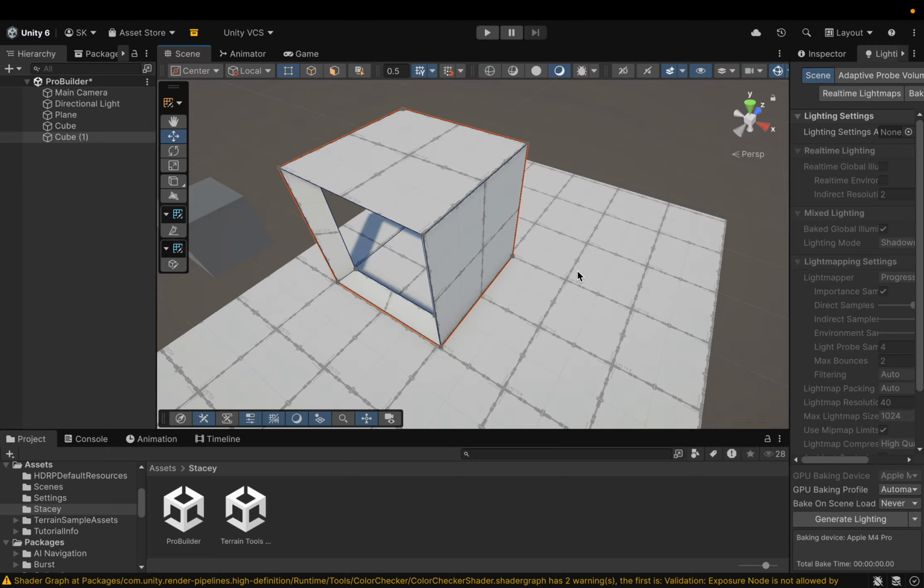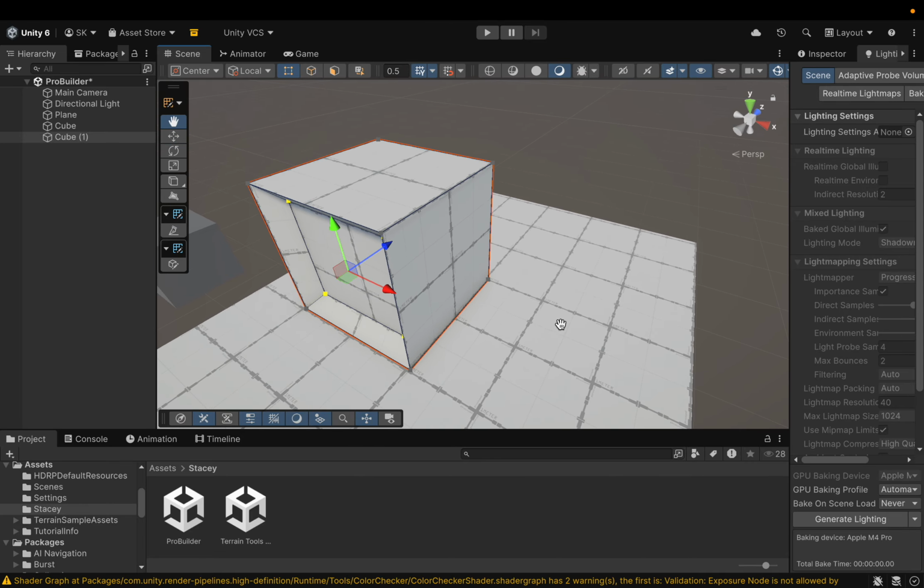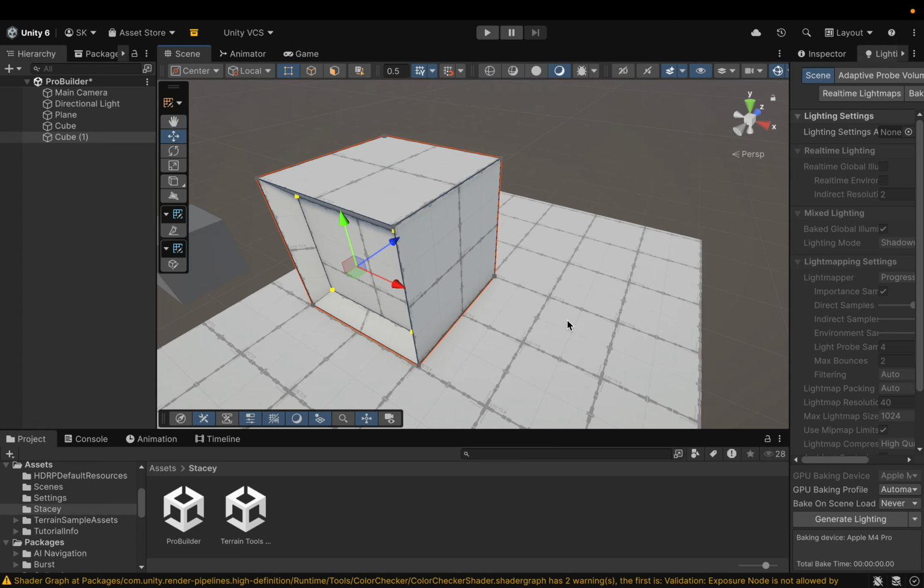I'm going to go back and put the face back on here. If I wanted to select multiple things, multiple points at a time or multiple faces at a time, I can hold the shift key down and drag across and select. So if I'm in, let's say, my face mode, and I want to select all these. Oops, I'm not in my face mode.